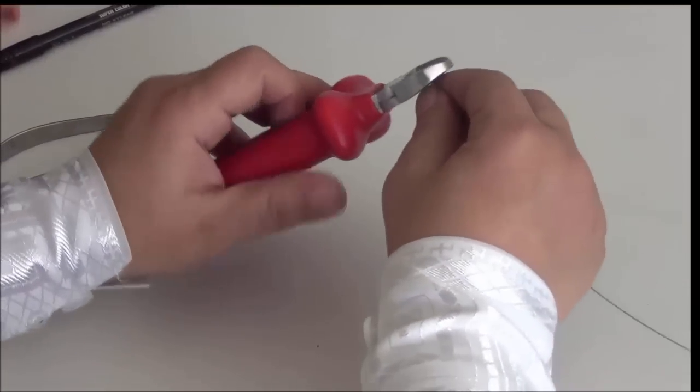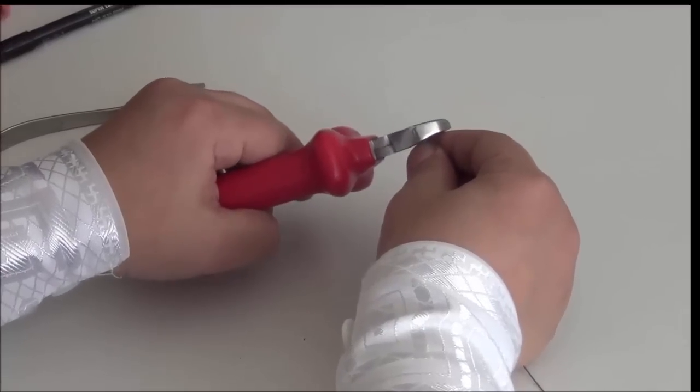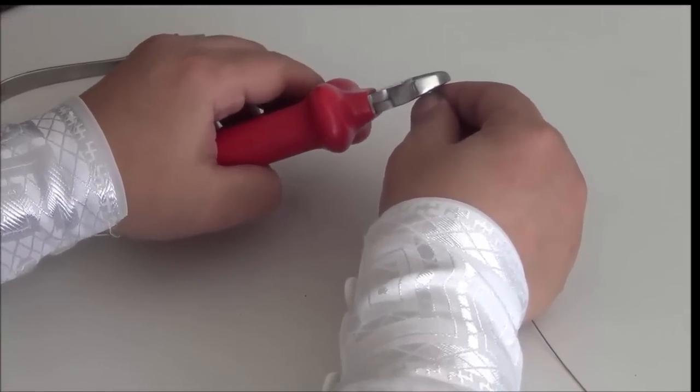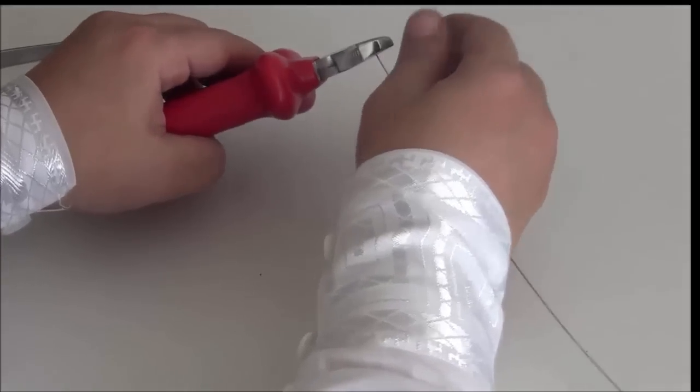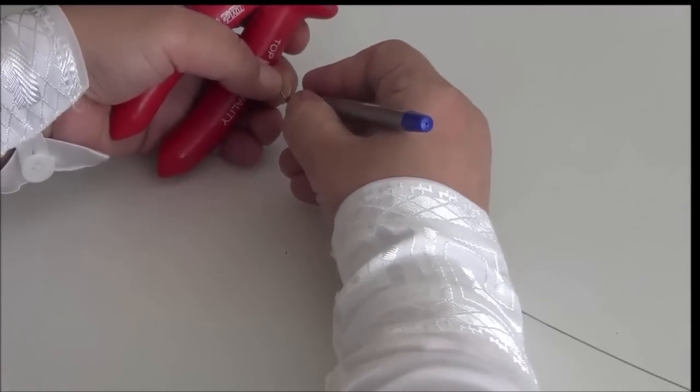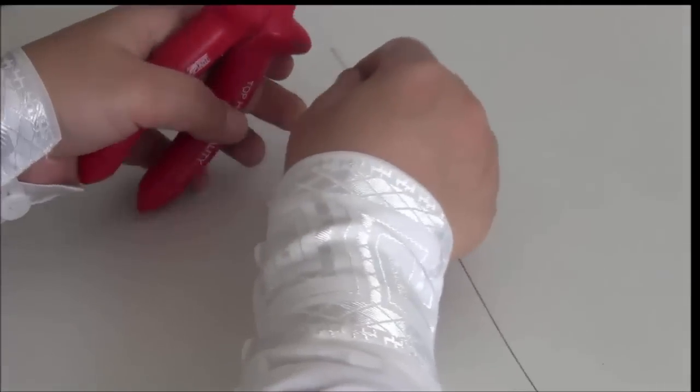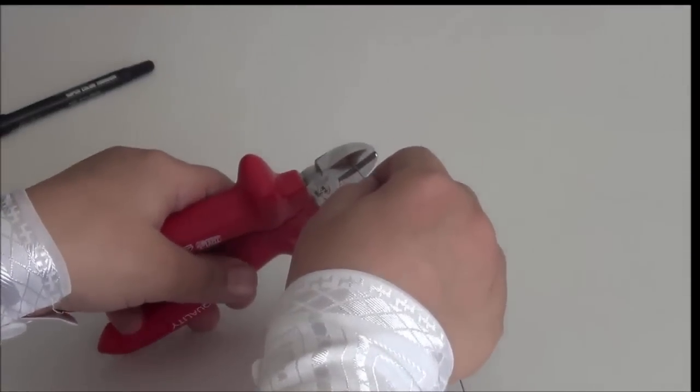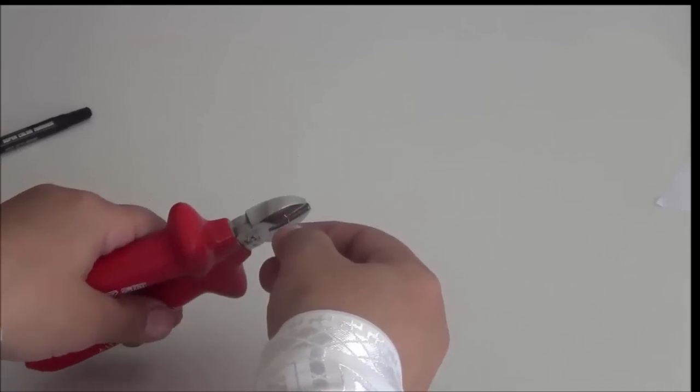So that means it might pose some danger to you and the colleague or colleagues sitting around you. So it's very important when you use the cutter that, once you have put a mark, for example, where you want to cut, and you place the edges of the cutter on the mark, you make sure that you protect the cut head with a hand. Just wrap it around, or cut beneath the table. You can go below the table and do the cut.